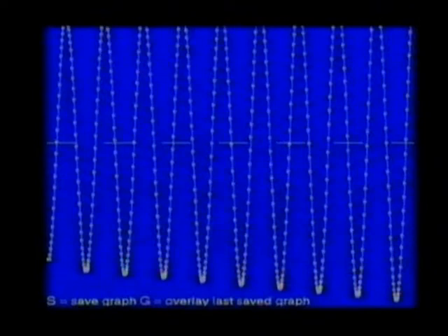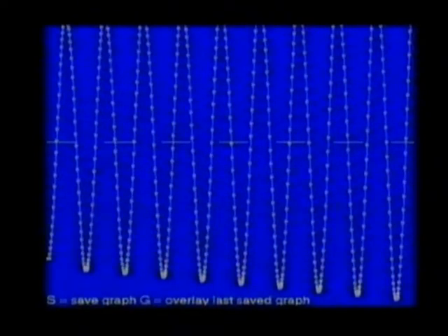Now I'm wondering whether we can go out of control with this. Remove the D term. This is proportional and integral only. This is going out of control. I wonder if we can bring it back into control with a hefty derivative. I don't know. I'm just experimenting to see what will happen. And it's done it. Well, that was a surprise. I didn't think it would with those values.